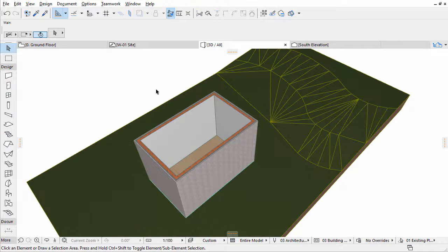We model the sidewalk area on the floor plan with the Slab tool as well. Let's assume that the correct skin settings are not available in the current project, but that we have used the right composite in another project before. In this case, we can import existing composites from other files. Let's see an example and add a composite from an existing project.